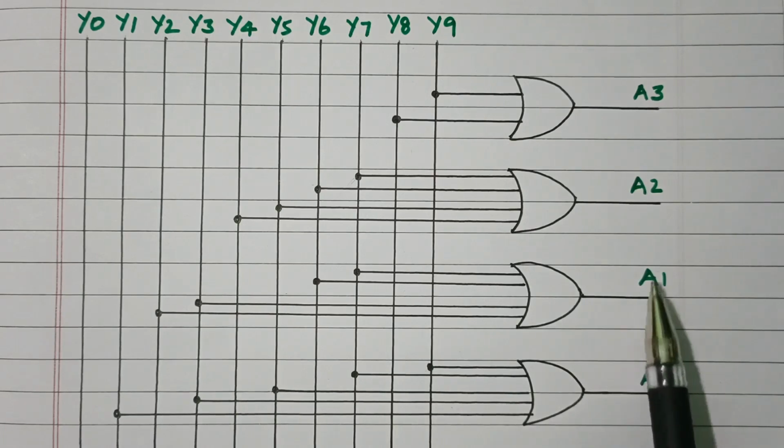So this A0, A1, A2, A3 is the 4-digit binary coded decimal with 10 combinations, 0 to 9. 10 to 15 we are not considering, as that becomes an invalid BCD code, so we consider only 10 inputs. So in this video we discussed the 16 to 4 encoder, that is decimal to BCD encoder. We discussed the block diagram and truth table. From the truth table we designed the logical expression, then the logical expression is implemented with the logic gates.